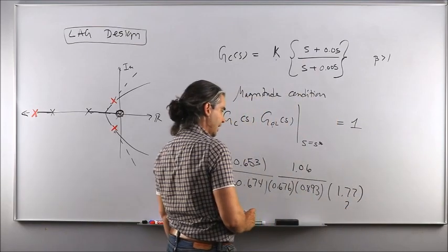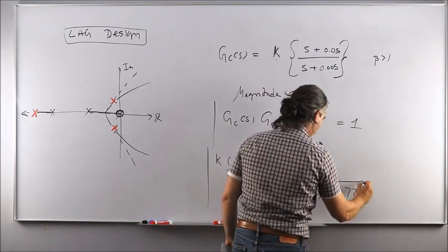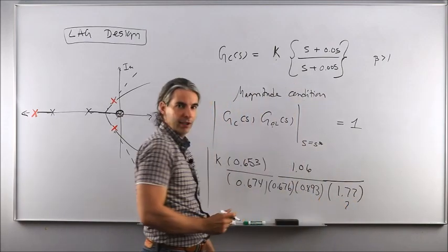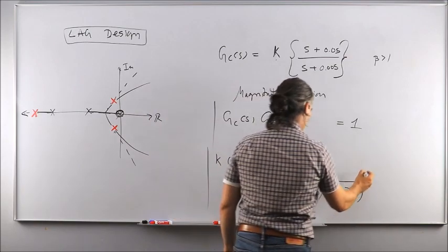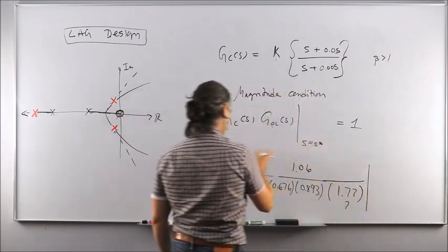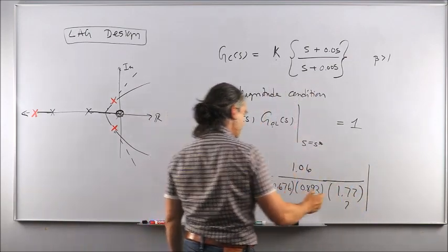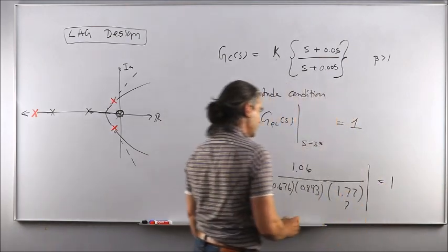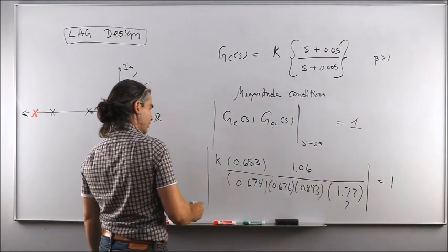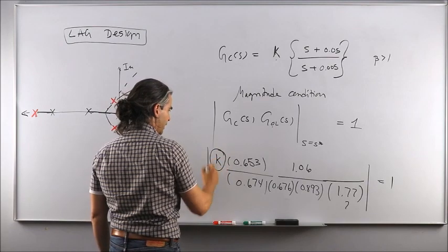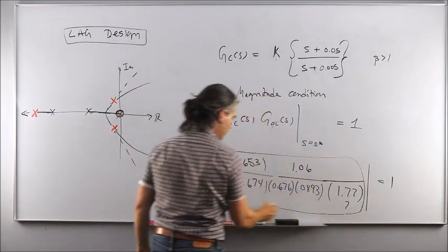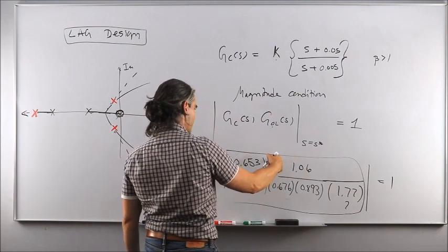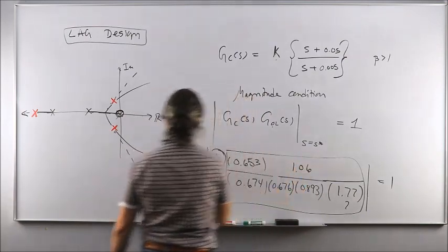I'll let you double check that again to ensure that you know how to design a phase lag compensator on your own, and do that prior to the exam, please. Okay, so the norm of all these things that were evaluated at S star gives me a 1 at the end of the day. So as you can see, the only unknown is the gain value K. You take this, that's going to give you one number. 1 over that number shall give you K,